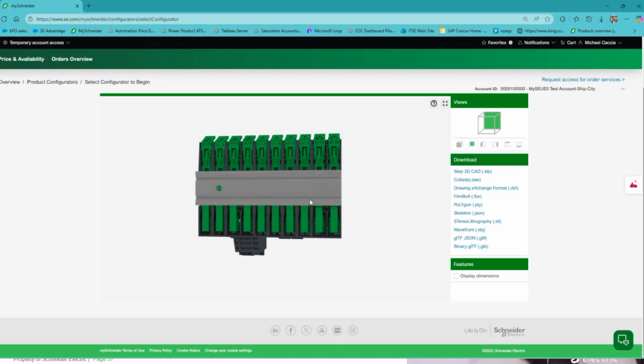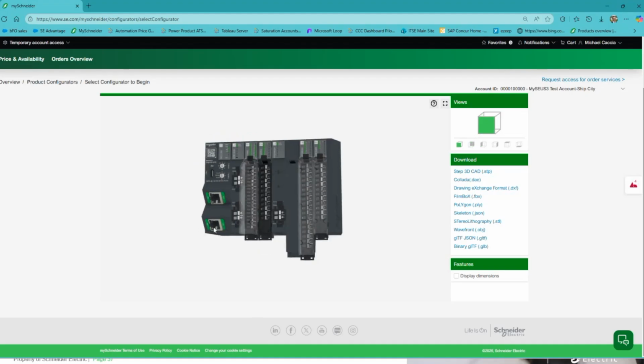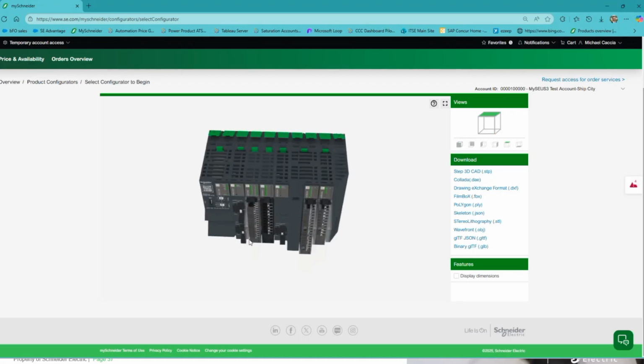I will say the way this rack snaps together is the first I/O module is put on the DIN rail, and then this module to the right will snap. You'll snap it on the DIN rail with a little gap, and then you'll slide it to the left, and it'll interlock with this one. And that happens to the neighbor and to the next door neighbor and such. And then you might want to know, well, how does it hot swap? There's actually these green tabs right here allow you to remove the module without disturbing the base that makes up the backplane. So this is how we hot swap the module.